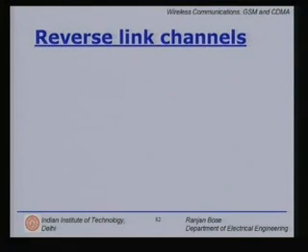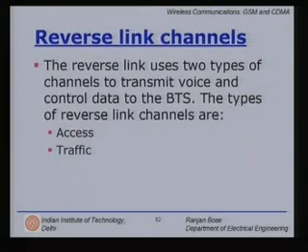Let us now talk about the reverse link channels, the channels provided from the mobile to the base station. The reverse link uses two types of channels to transmit voice and control data to the base station. The types of reverse link channels are access and traffic.